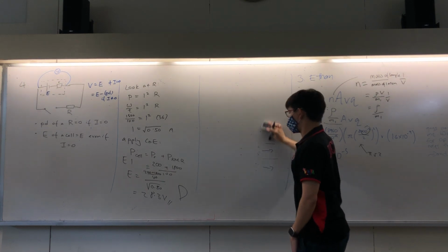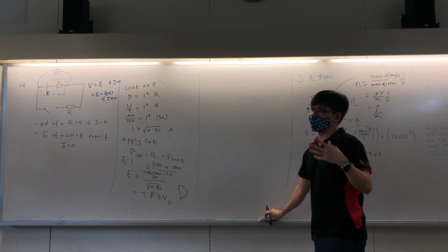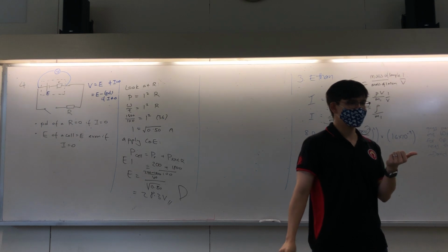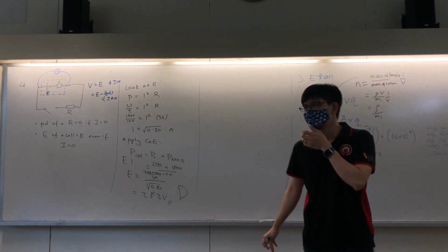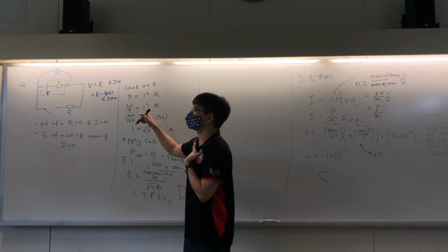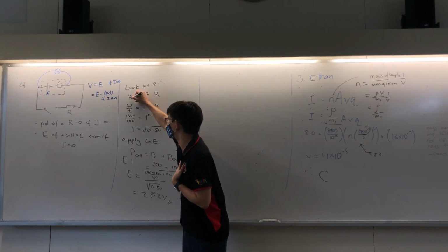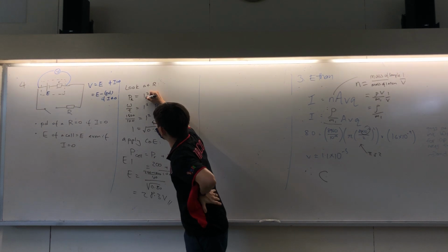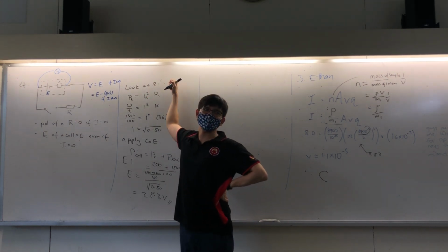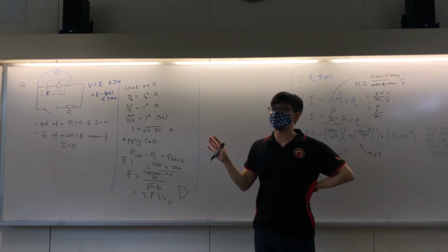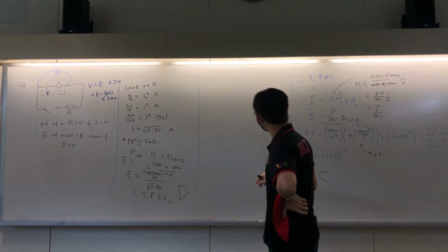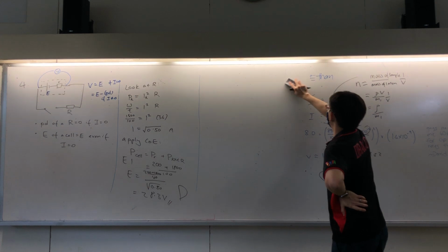So two concepts to consider here are conservation of energy and V equals IR. Keep applying them again and again. But just be careful when you use equations. It must be the power developed in R, the current in R, and the resistance of R. So all must be for that one object. Don't anyhow use V's and I's, that's where you'll make mistakes.